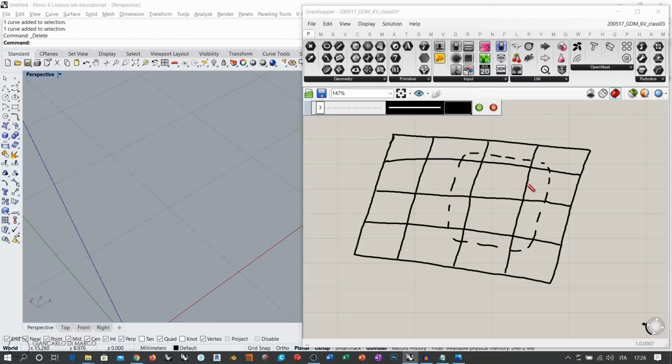And in order to do this, the mesh cannot maintain its original resolution, because in that case, well, basically you will only have the possibility for these vertices to move inside this shaft, but you will maintain the resolution. So if this vertex moves up like this, then this edge would simply pull the other vertex, and eventually you will get this effect. So when you want to produce some kind of growth or differential growth algorithm with a mesh, you must increase the resolution.